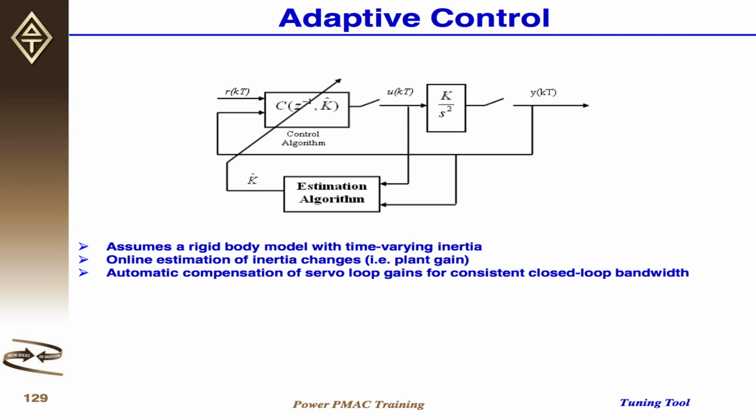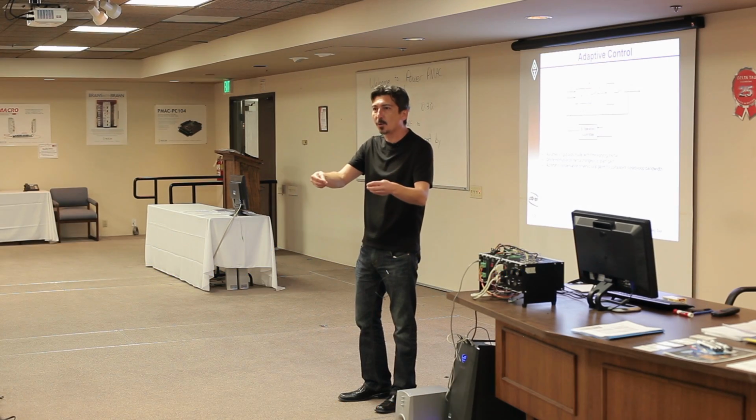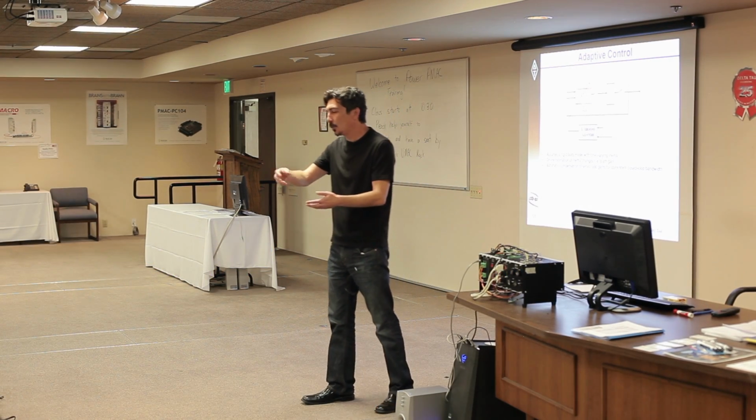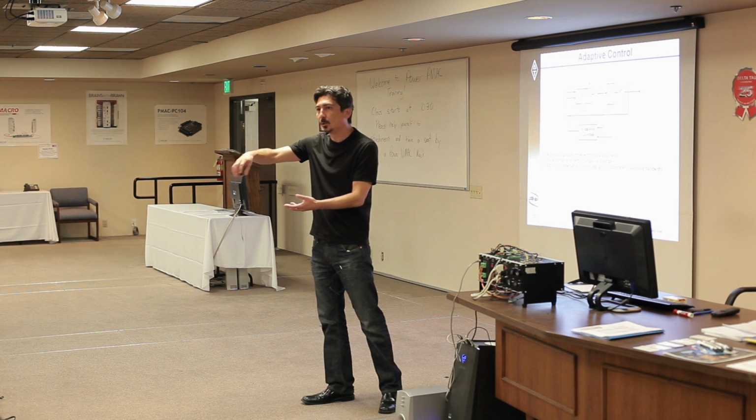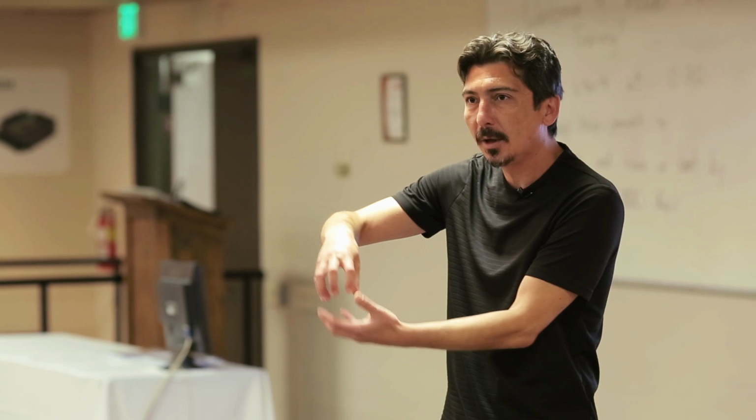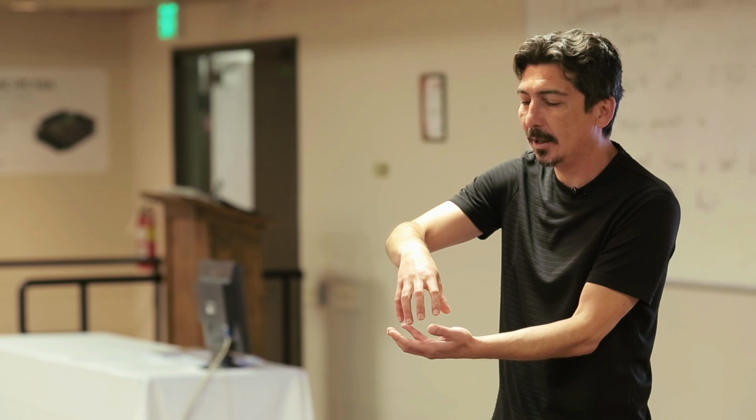But if you do know it, then of course you can use what we call gain scheduled adaptive control. Let's say you're changing the tooltip for a robot and it has different loads, then you can change your gains accordingly, because you know when you grab that end tool.